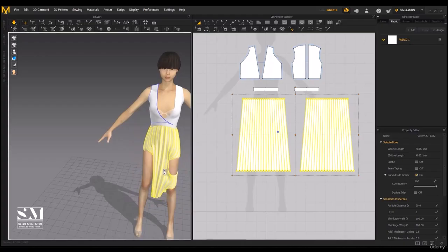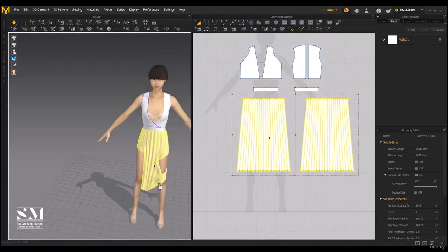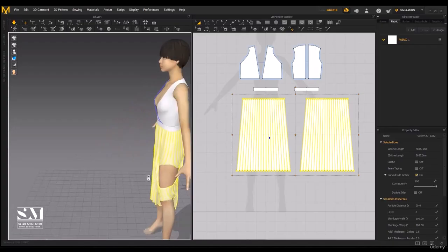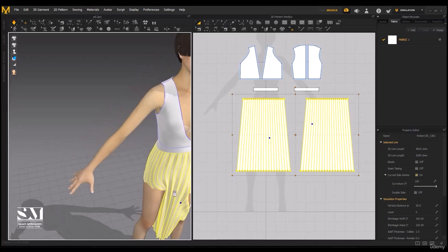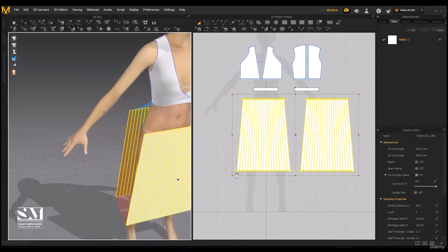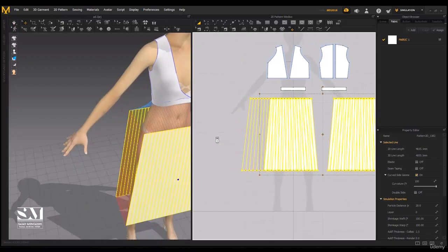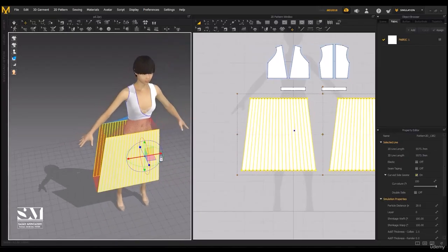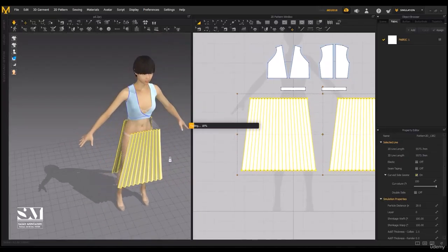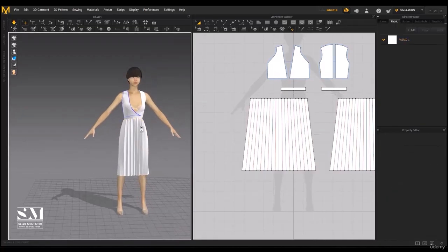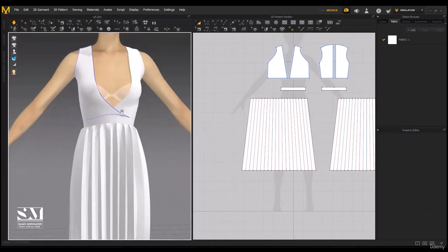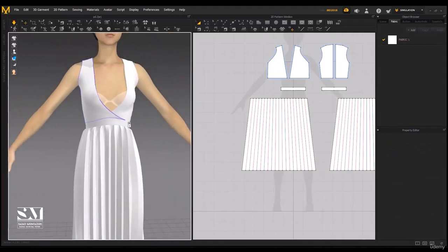If you see the plates still look too cramped for the number we defined, press Ctrl plus Z, increase the width further, and here Ctrl plus Z, increase it like this. Very good. And again, it's based on your design. Pay attention. Place them again and press space. Now here you see it's fixed properly and it's better, I think. Very good. At this point, the upper garment has already been simulated and doesn't need to be recalculated each time.